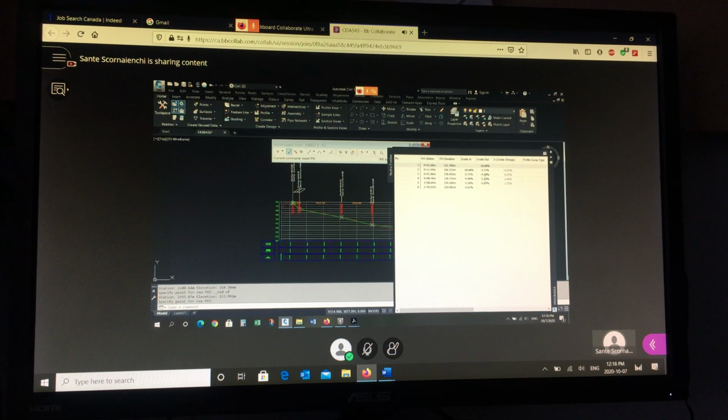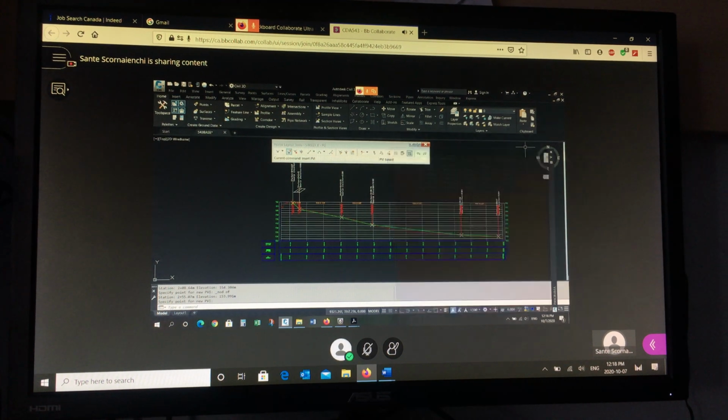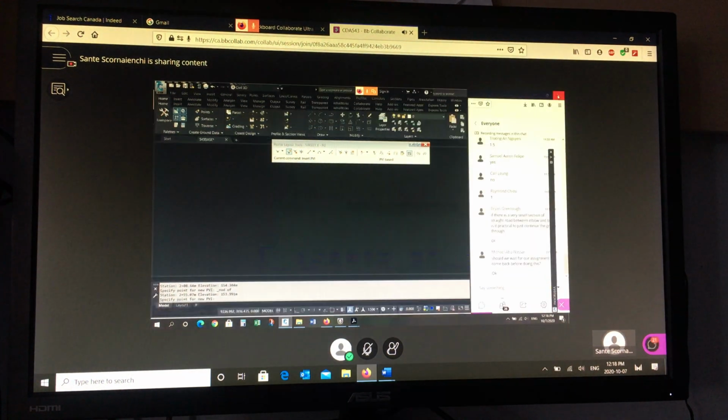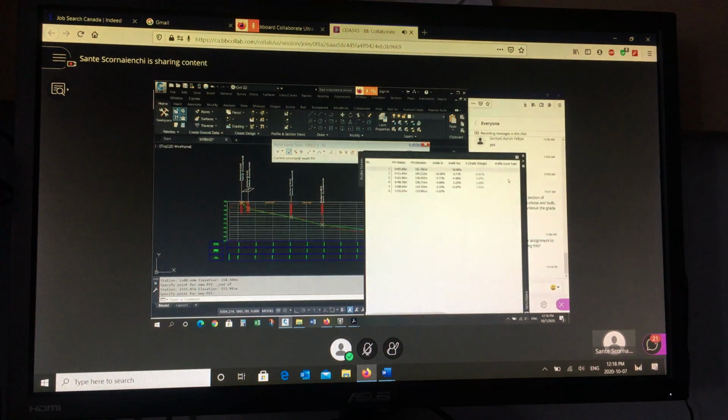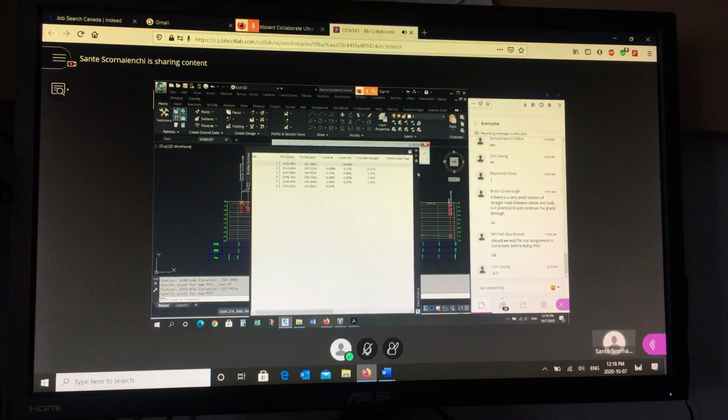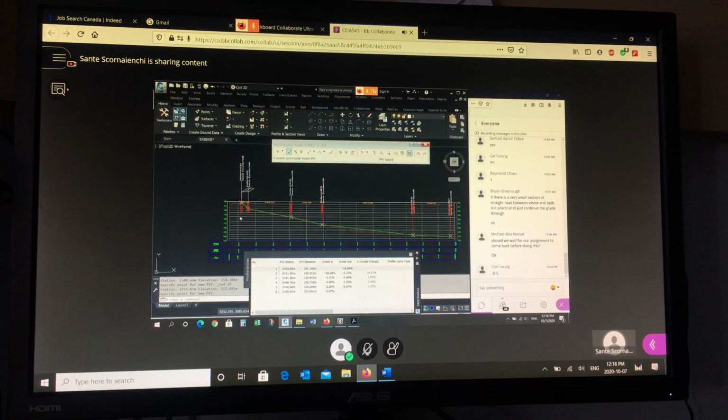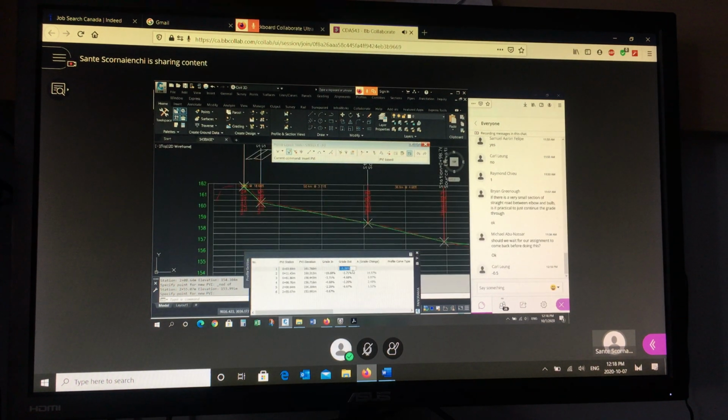And I put in the slopes. Start at the beginning and work your way to the end. So what's the first slope supposed to be? Anybody remember? That's my profile. Negative 0.5. And you can actually, this is dynamic. As I change the numbers, it's going to redraw. Right, so watch here. So this one here should be negative 0.5.